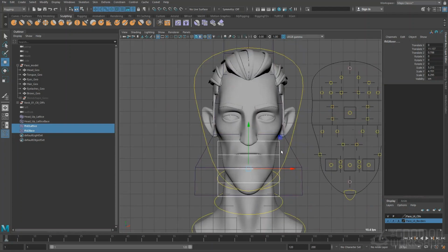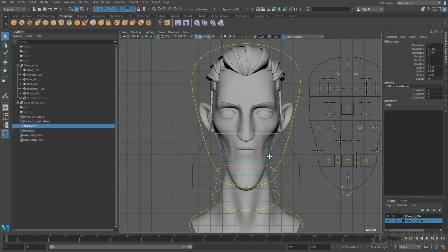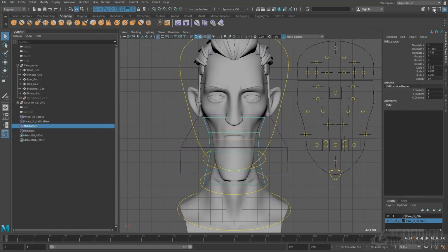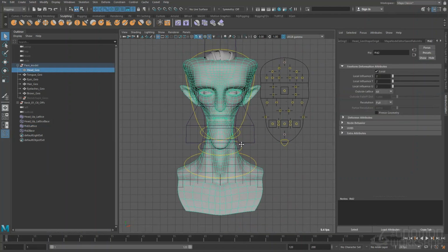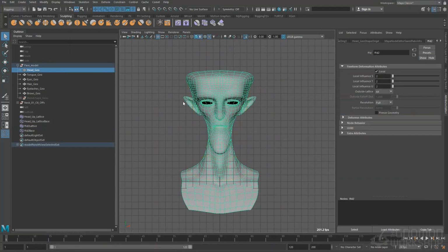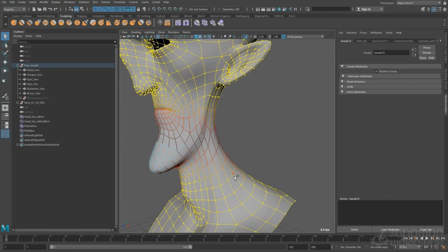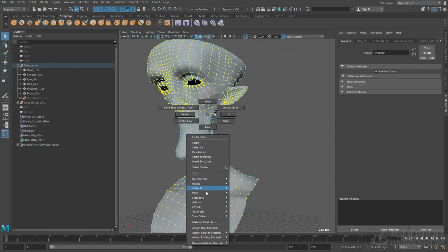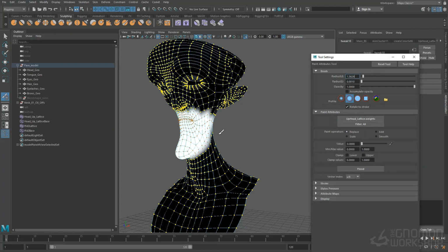And I am now going to shape this. The same, I need to change the outside lattice information to all. This is going to work like that, I know, but I am just going to skin now. So I'm going to skin my lattice. I don't want this, neither this, to be influenced by my lattice. So I am going to remove all these weights. Replace to 0.